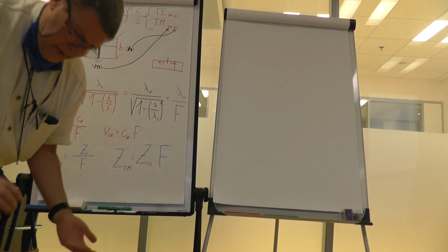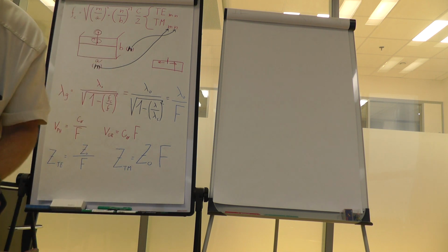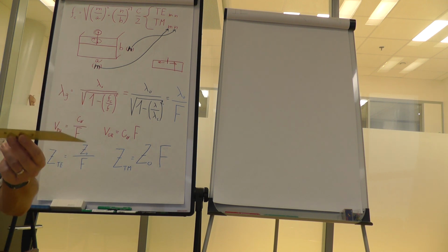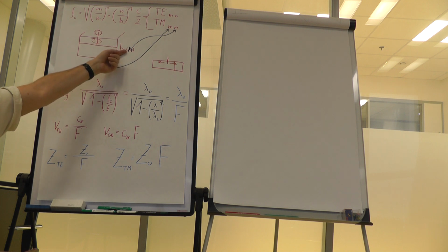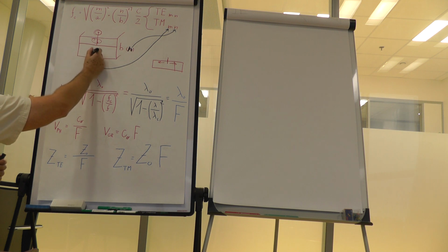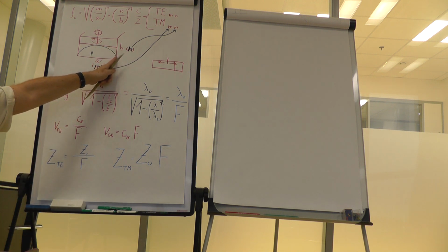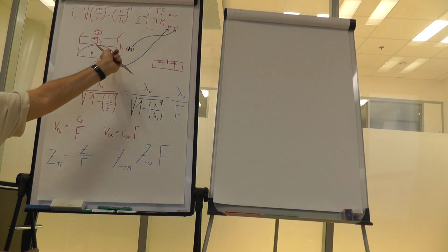Well, why do we do that? That's quite simple. Imagine first that this material is lossy, partially conductive. So if we position it at the wall of the waveguide, remember, the electric field is oriented in this way, but the magnitude for the dominant mode gets to zero because that component of field is tangential to a metallic wall, and it must be zero at the surface of the conductor.